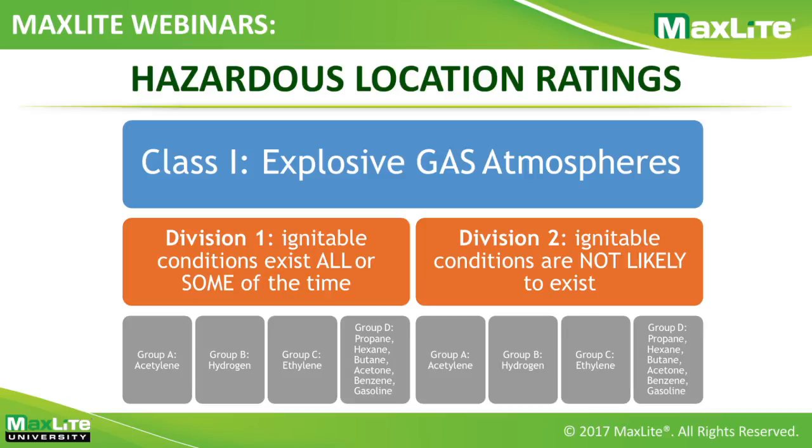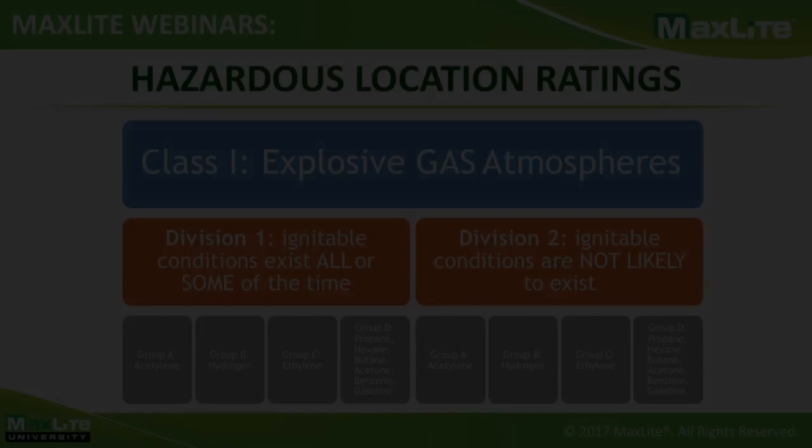Essentially, the whole point of hazardous location lighting is that even when you have volatile gases such as these present, your luminaire has to have some type of rating to ensure that, depending on the levels of the gas and also the volatility and the vapor pressure of the gas present, your luminaire can be used in that location and gas won't enter and therefore spontaneously combust.